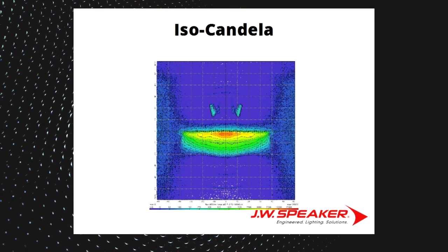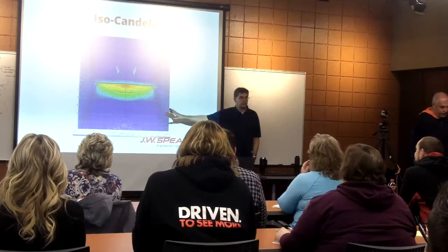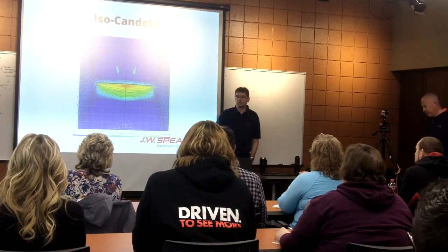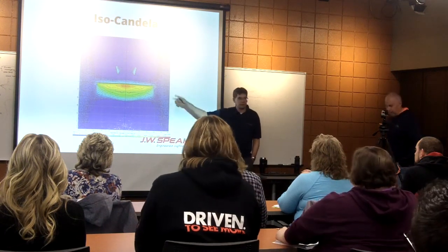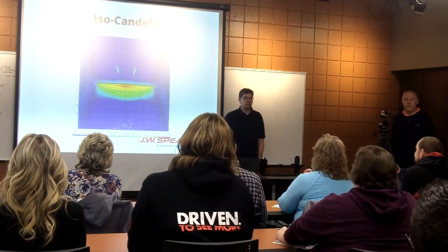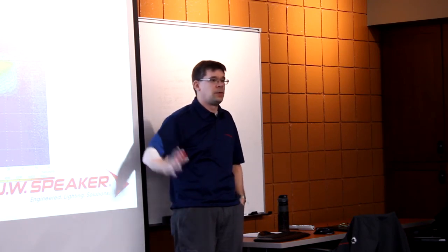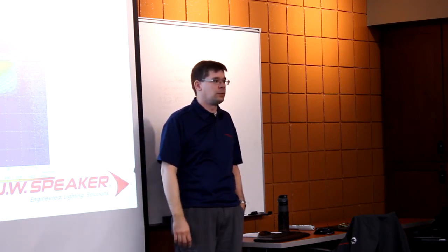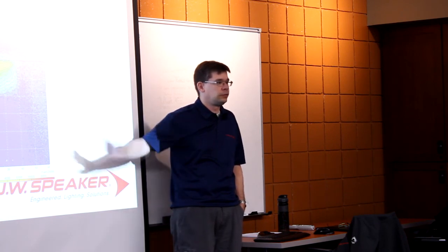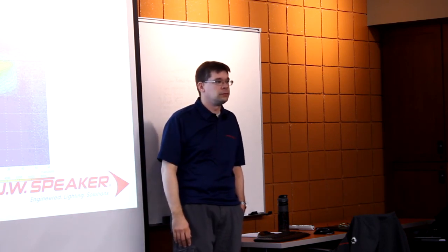One more aspect on this diagram, it might be small here, but at least in this particular format, we have our lumen value. That is the total amount of lumens produced by this lamp in this window. As a standard, we use the ±60 by 60 window for all of our lamps. For some of our really wide lamps, we might have to measure a little bit wider, but the 60 by 60 window is our standard.